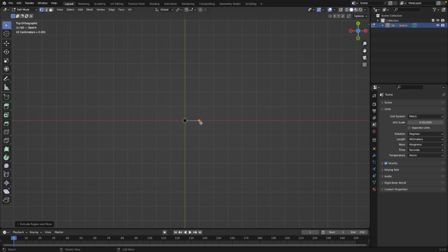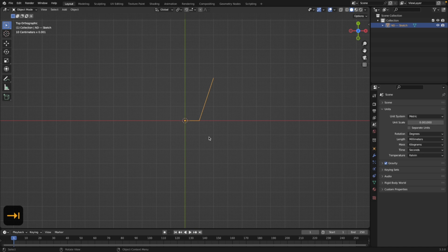And actually, I'm only gonna create half of this shape. So this is the first thing that's gonna be slightly different. I'm just gonna bring it up to like here. You know what, there was more of an angle to that. So we'll bring it up all the way to like here. Yeah. So this is half of our trapezoid shape. The other half obviously could be over here, but rather than drawing that and trying to get it exact, I can actually just mirror this thing, right?